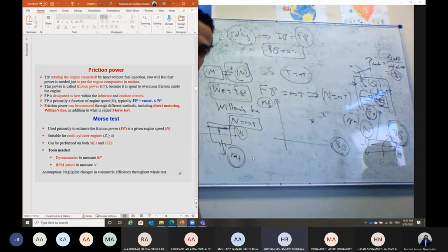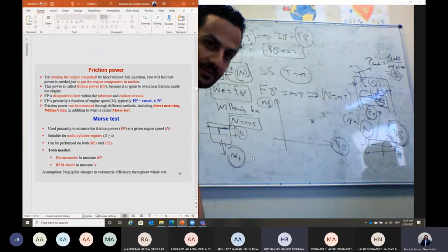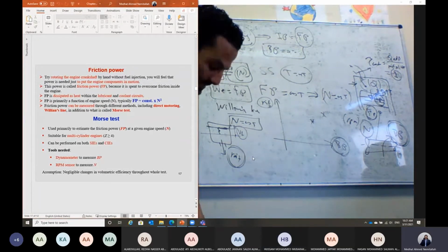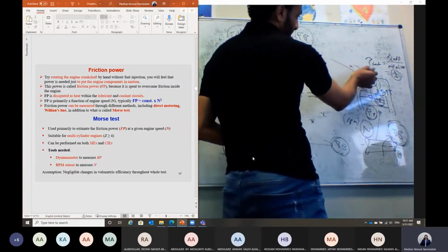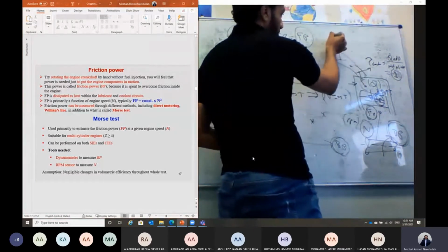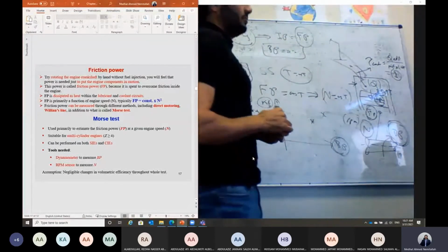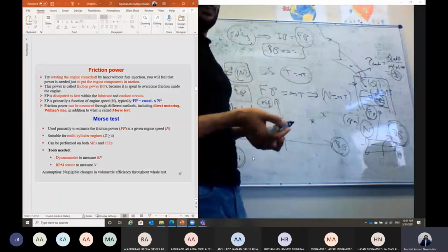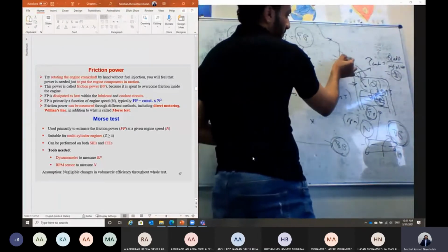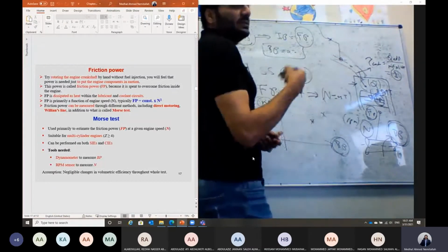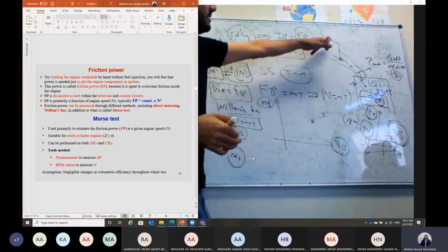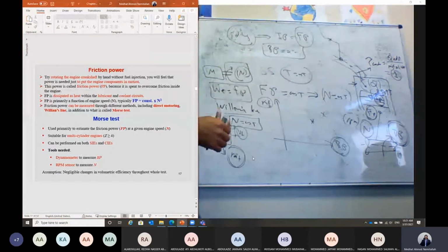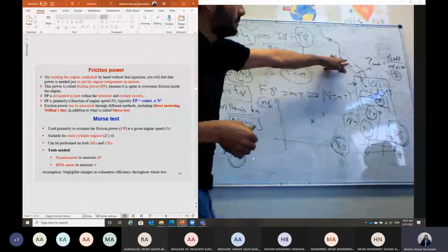Throttle valve. Exactly, the throttle valve in this case. Here in the intake manifold, we have the throttle valve, which is connected to the accelerator pedal, which you just press with your leg. When you need more power, you open this throttle valve a little bit more, and in this case it will allow for more air. If I need to reduce the brake power, I will just raise my leg. Then we close the throttle valve partially, and we can reduce the brake power.